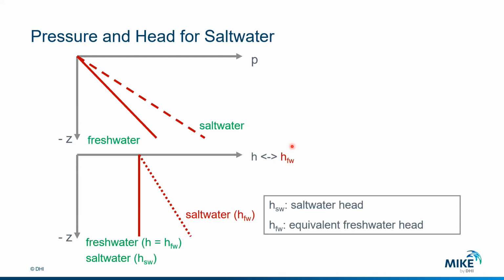In the case that you have data, for example you are measuring piezometer data in locations with high density, you will also need to correct your measurements for density before you put them into FEFLOW and before you compare scatter plots or do a calibration. Otherwise, you will immediately have an offset between your measurements and your simulated results.